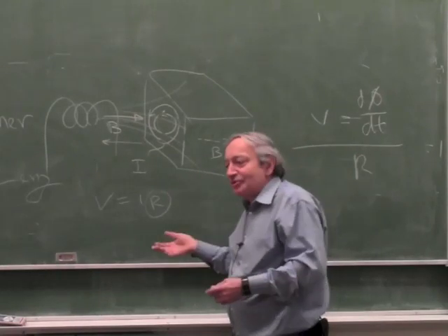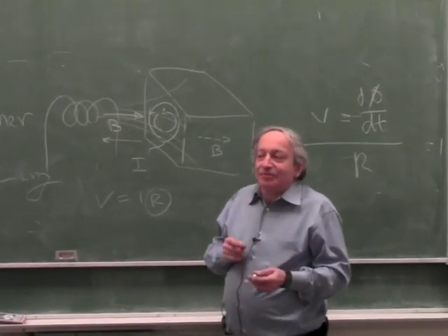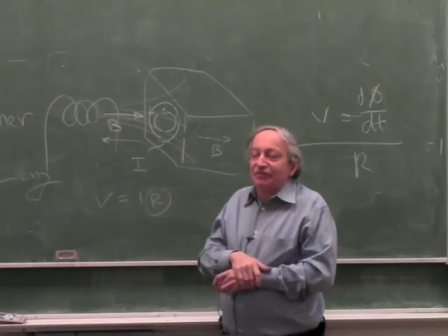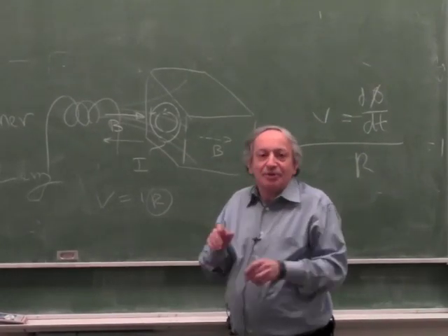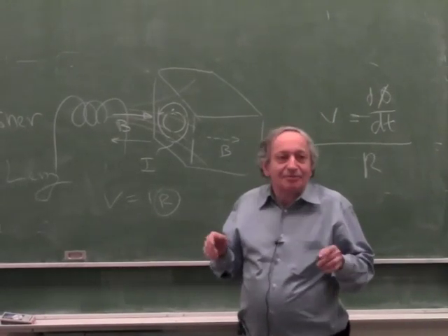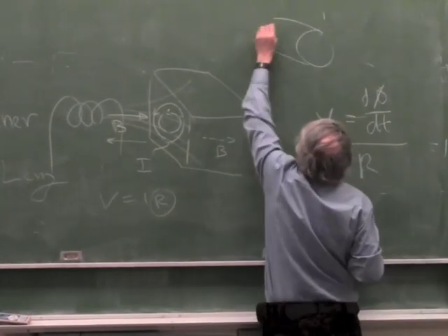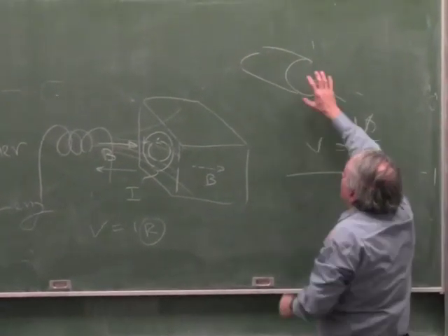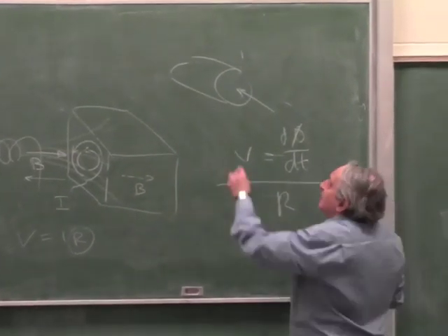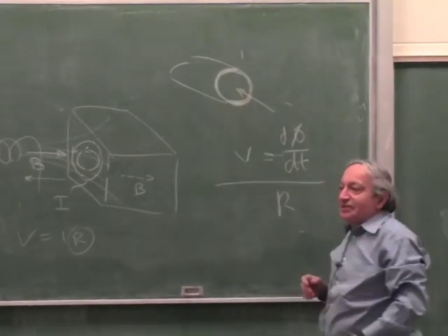If copper is not so good for low frequencies, steel is not good for high frequencies. By the way, the reason steel is not good for high frequencies is another reason called skin effect. Okay, how many people here know what skin effect is? Okay, more of you should know. When you run a current through a conductor at low frequency, the whole cross section carries the current. At high frequency, the current is only sitting on the outside and cannot penetrate inside the conductor.